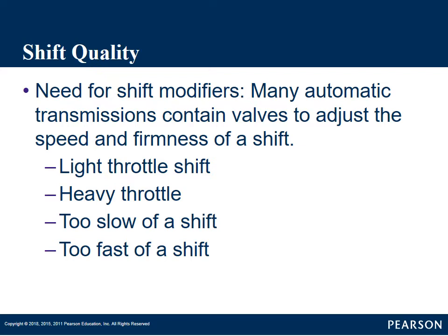But as we started adding more gears, people expected more comfort out of their vehicles, that they wanted the transmission to shift a lot smoother. They didn't really want to feel those shifts. So they had to start adding valves and accumulators to start compensating for that.